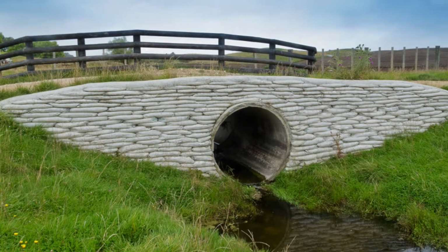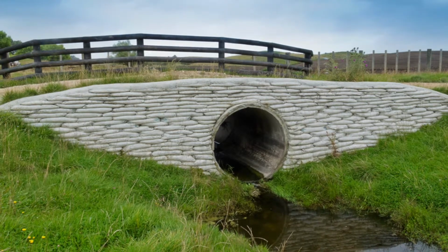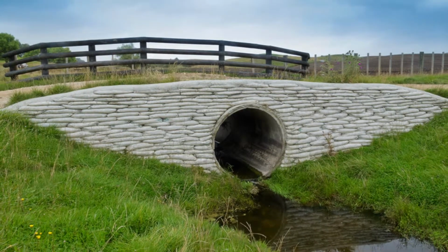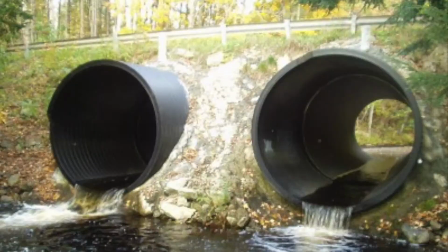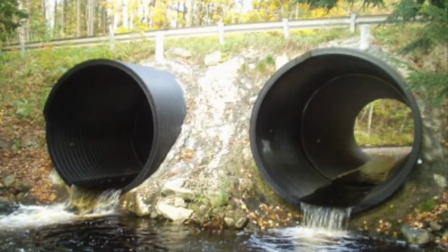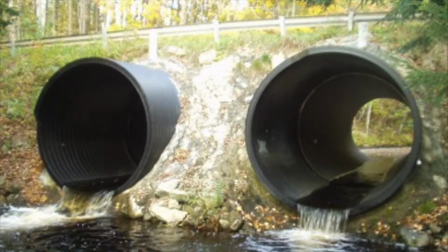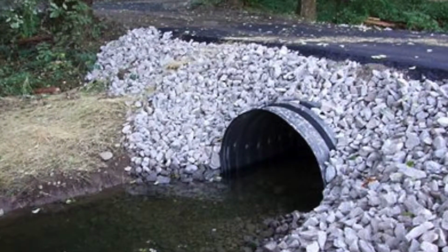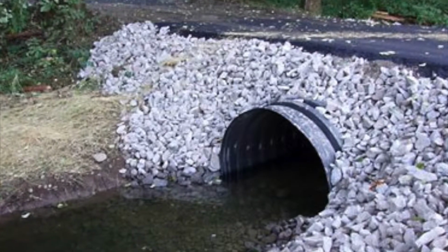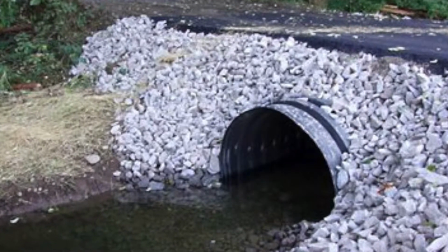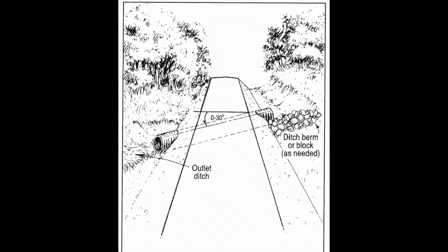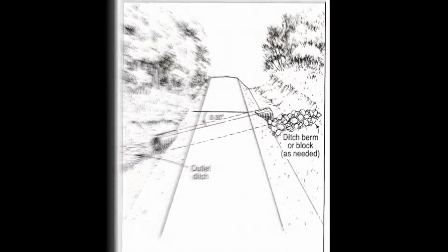They're critical for preventing flooding of communities during normal and extreme weather conditions, as well as being integral to proper road and highway maintenance. General design considerations for culverts include the size of the culvert, depending on the necessary flow rate based on volume and velocity of water passing through the culvert with respect to time, the material of the culvert for corrosion resistance, as well as the soil used in the culvert system.